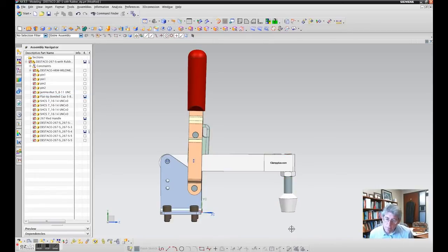So that means this tip can exert 1,200 pounds down on a clamp specimen, or in other words, acting up on this point, there could be 1,200 pounds, right? So that would be one load condition. Nothing happening with the handle, but simply just 1,200 pounds acting up at this tip.